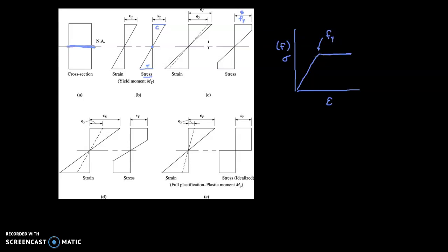However, if we look at the way the stress is distributed throughout the beam, although we may eventually get to the yield stress at the top and bottom extreme fibers, as soon as we go inward to the interior of the beam, those stresses decrease. They decrease, and in fact there's zero stress at the neutral axis. So what happens essentially is, if you design the steel beam to only accept loads up until the point when the outer extreme fiber yields, then you still have all this additional strength left in the interior of the beam that you're not taking advantage of.